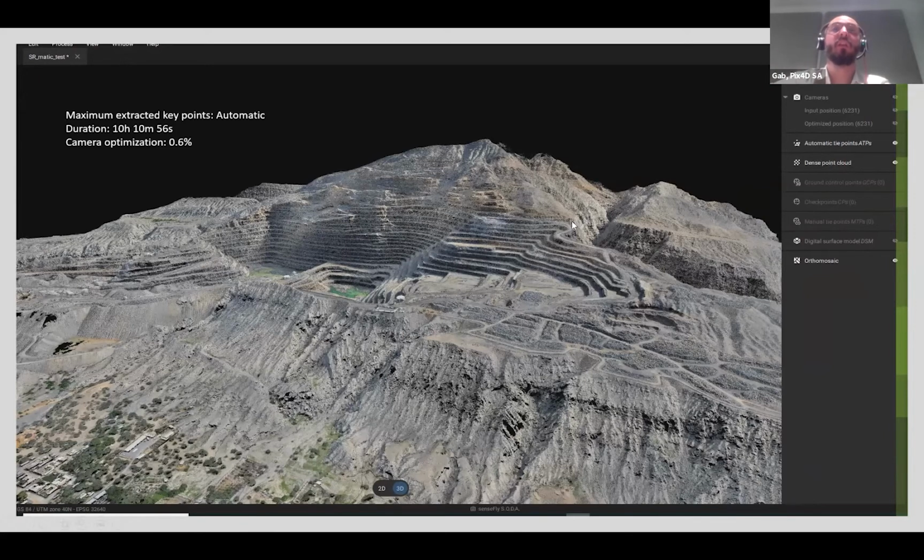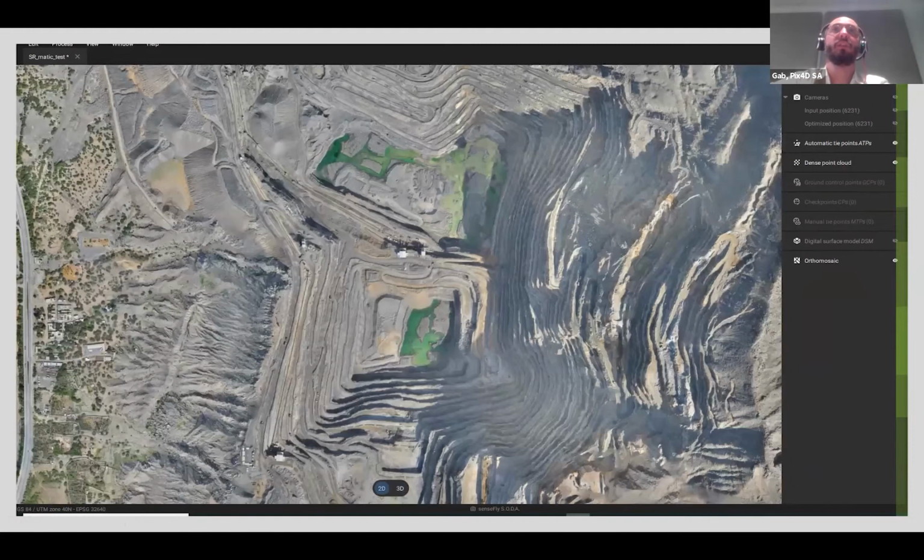The interesting thing here is that the orthomosaic was also generated together with the DSM, in really a fraction of the time that was used with the normal software. The sets of images were flown and acquired in about 20-30 minutes each, and basically in one day the FEDS experts, drone pilots, acquired and surveyed an area that was previously surveyed in basically 2 months. Only 25 ground control points were used, and basically led to that type of accuracy. A lot of them were used as checkpoints, and the results are pretty cool.